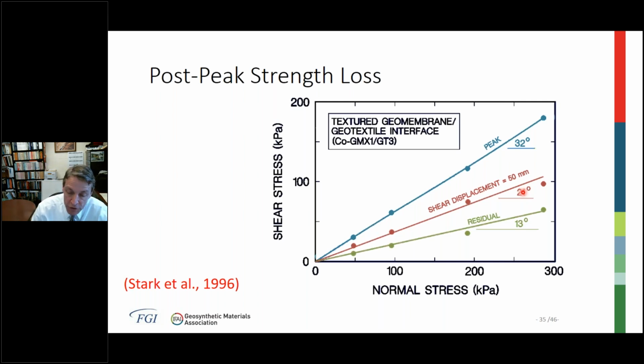I think it is a hole because as construction proceeds, these slopes can be steeper than the final configuration of 4-to-1 or 3-to-1. And that's because maybe there's a delay in the construction of the expansion cell, and thus waste continues to be placed, the toes excavated. So I think there's been enough problems with interim slopes that at least the design community should be considering it.